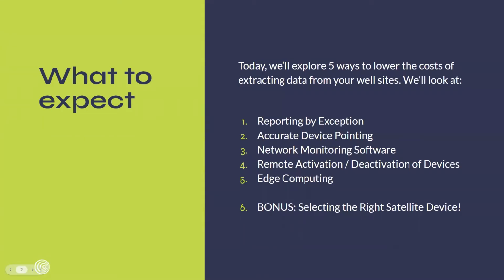Today, we're going to look at 5 ways to lower the costs of extracting data from your well sites. We're going to look at reporting by exception, accurate device pointing, network monitoring software, remote activation and deactivation of devices, and edge computing. And we've put some bonus content in here about selecting the right satellite device.